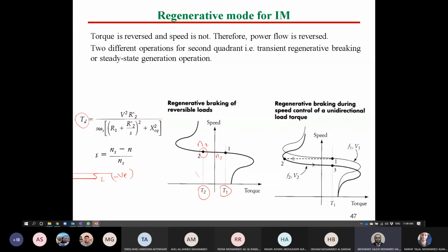No, I mean because it became negative since our speed exceeded it. So is that a normal thing? Yes, it's normal. This is the conversion from motoring mode to generating mode. And we discussed the modes of operation before. The example is like the motor is going downhill.